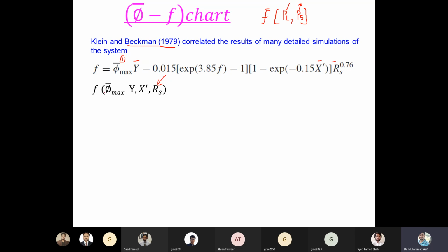When will the value of phi, the utilizability, be maximum? What do you think? In relation with the critical radiation. Anyone? When will phi be maximum? When critical radiation is lower, or the radiation losses are lower and the incident radiation is higher.